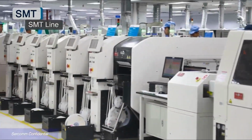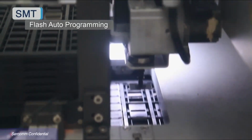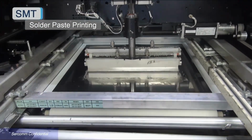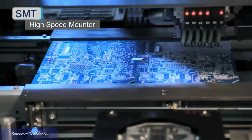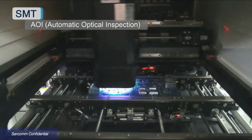So SMT means surface mounted technology. Those are all the little components that basically sit on the board and that get basically glued on it, and then they heat them up. And so they put a paste on the board. Those little components get stuck onto that paste, and then they get heated, and that becomes solder, and the components are soldered to the board. Maybe I'll just shut up and let you look at it.